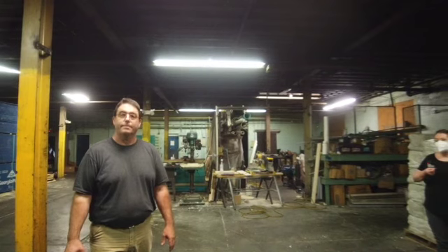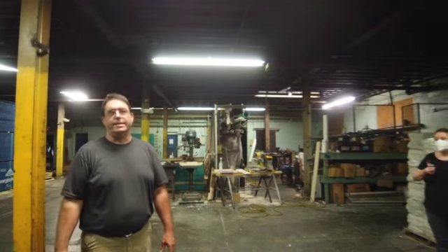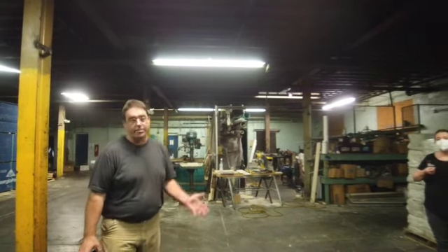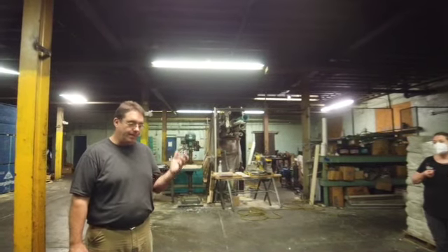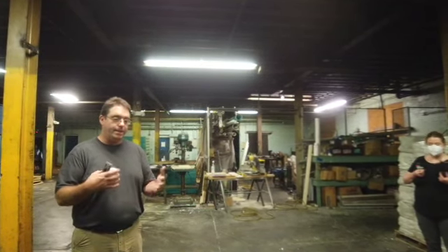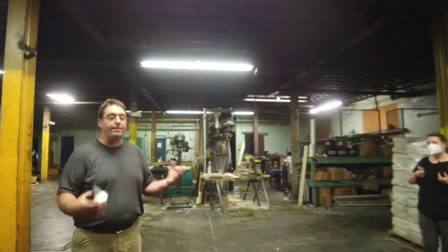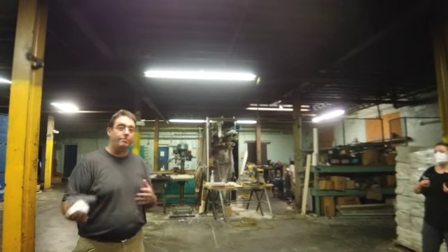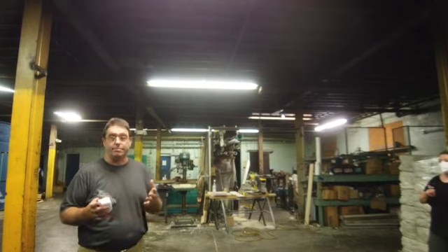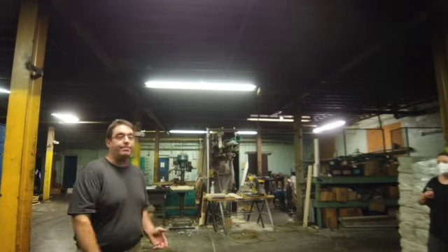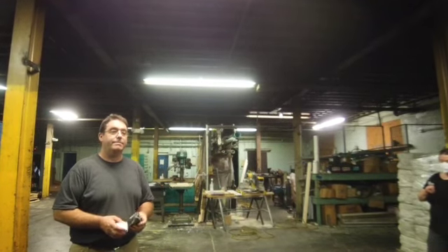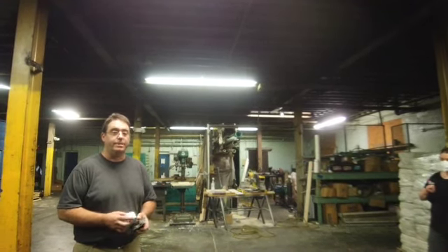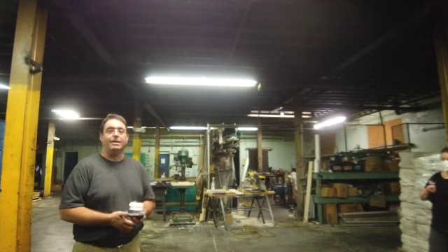So I imagine that'd be kind of fussy to transport. It is. It gets damaged easily. The same with the MGO board. If you think about your panel seams being the same as your drywall seams, if there's any movement in the building, shrinkage, racking, anything, those seams are going to crack. And so then you have to go back and tape all those seams again and clean everything up. So there could be some ongoing maintenance issues with it.